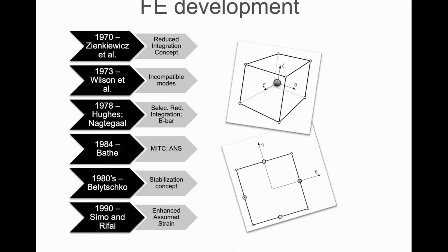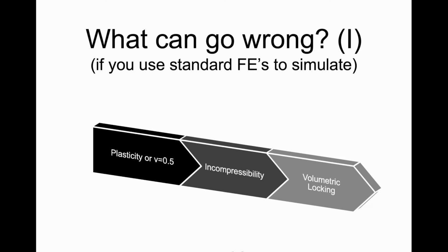The reduced integration is the C3D8R element that we are going to address. And in 1978, what we call the selective reduced integration, that is basically the C3D8 standard element. So as you can see, the standard Abaqus element is not really standard when compared to the books. It's the selective reduced integration. Things evolved, and until today you can see people publishing in this area.